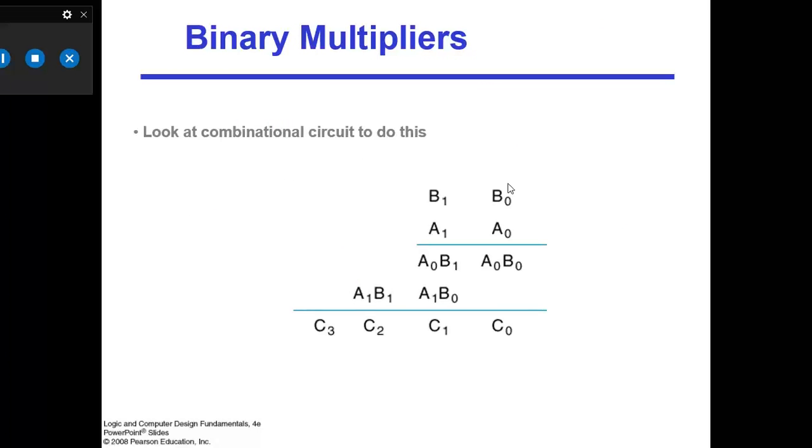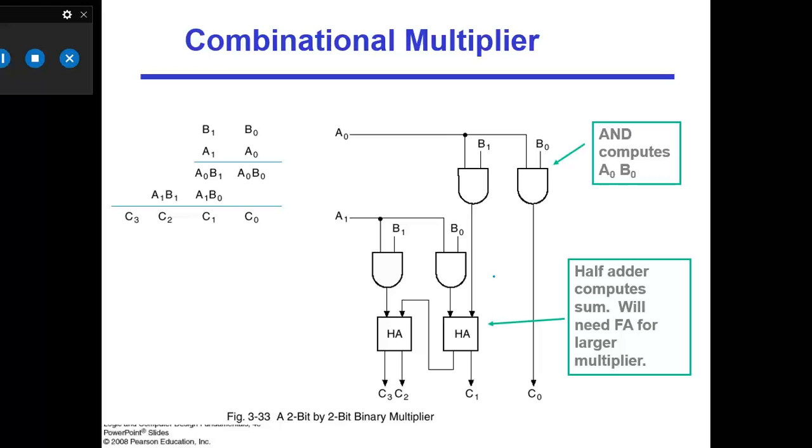So binary multiplication is an important thing as well, in which we multiply the terms a0 a1 by b0 b1. These are 2 bits. Let's say this can be 1 0 1 1. So we can multiply a0 b0, a0 b1, and then a1 b0, a1 b1, and then add them. This requires AND gates and adders, and we can basically make a multiplier, which is a very important aspect for computation in digital logic.